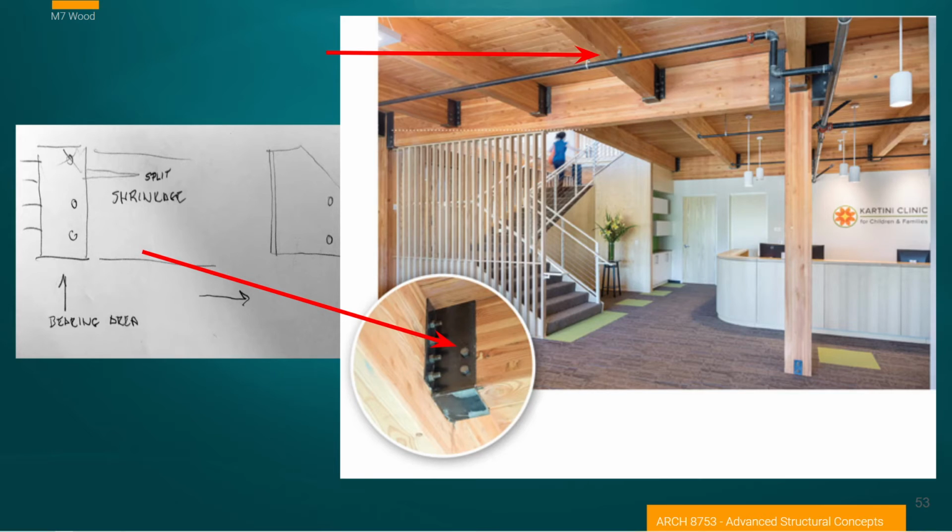But I find in this case, because the building had to be sprinklered for whatever reason, it might be a secondary reason, it might have been a primary reason, they don't need to protect these from failure in a fire because they've got a protection system for that. At least that's my theory on that. And I think the connectors become a very interesting element.